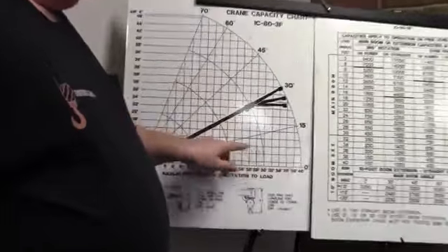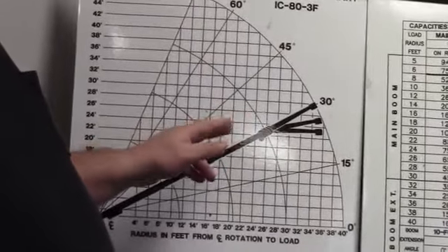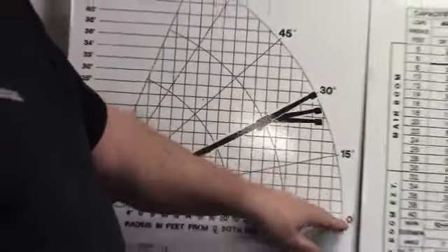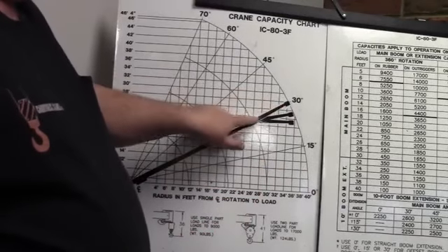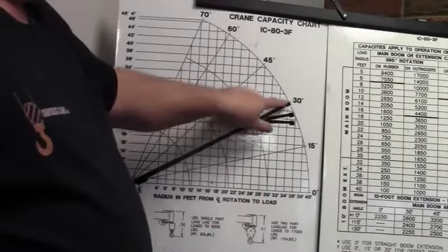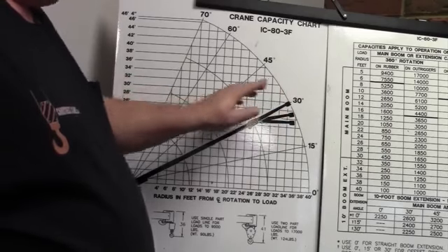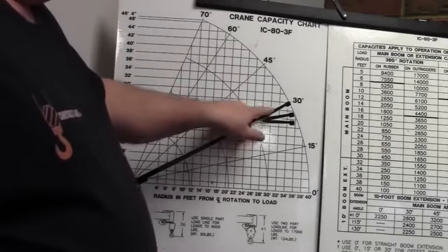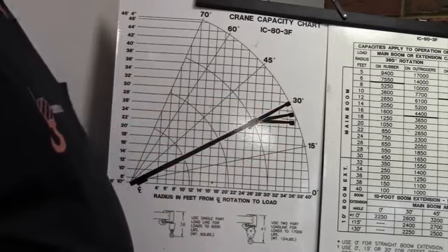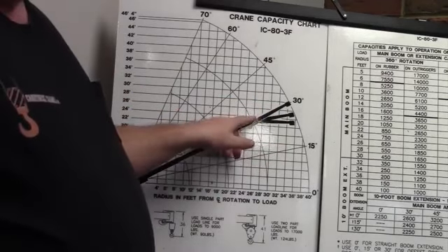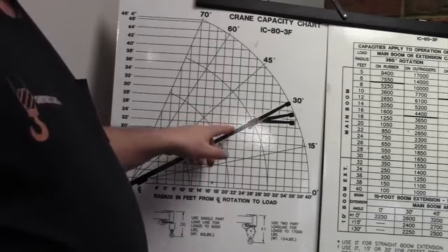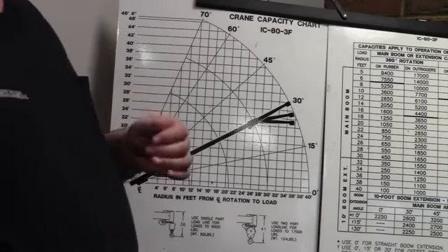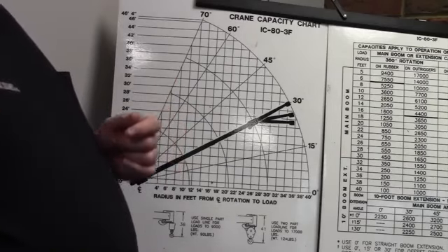Your third arc is with the main boom extended all the way, with both telescopic sections moved out to the end. And then this final fourth arc is with the jib fitted in place. You'll notice on this picture that the jib is either straight or what's called luffed, or offset, either at 0 degrees, 10 degrees, or 15 degrees. Some cranes are equipped with a luffable or offsettable jib. Some cranes are not. Most of the time the jibs are fixed and held in the 0 degree position. So the first thing we have to do to be able to calculate the capacity of this crane is we have to know what the load radius is.